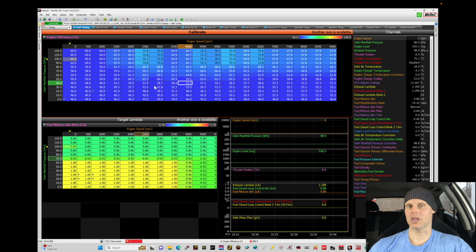If we have a different cam profile, obviously we're going to have different cylinder filling. We'd like to have a table dedicated for low cam and a table dedicated for high cam. Same with spark timing. We're typically going to run a couple more degrees advance from low cam to high cam on our K-Series engine. And our variable cam target definitely changes going on the high cam profile. So we need to make this all work on one table. Now it's not impossible to do this, but it's definitely not going to be the most ideal way to handle things. How do we go about setting this up?